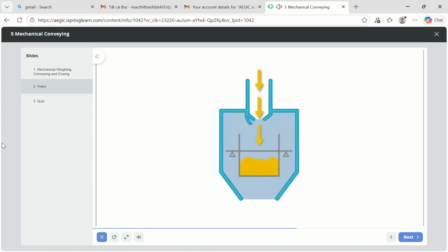Batch weighers measure flow rate by collecting a batch of the material and stopping the flow temporarily while an accurate weight is taken. The materials are then removed so that a subsequent batch can be measured. The time taken to collect each batch indicates the flow rate. The process following a batch weigher must withstand receiving material in dumps or batches rather than in a continuous flow.